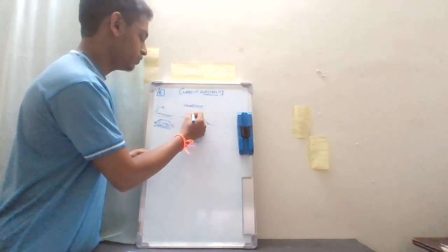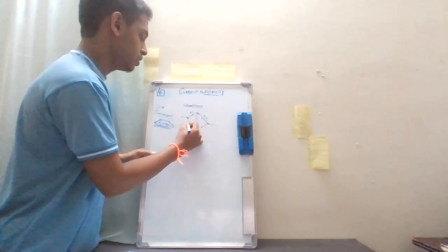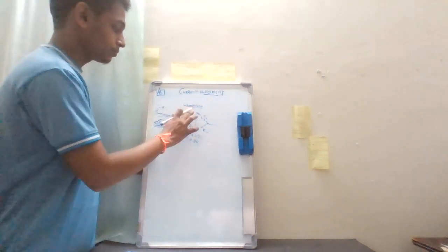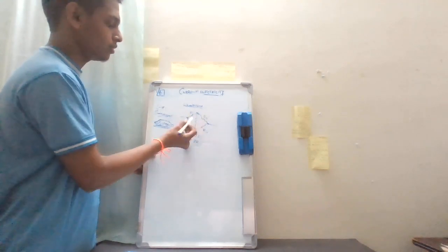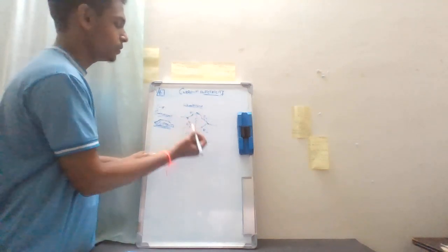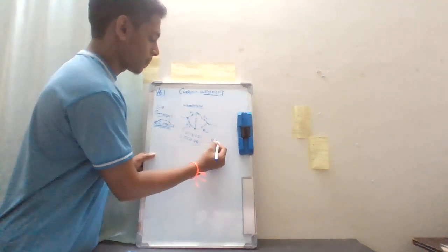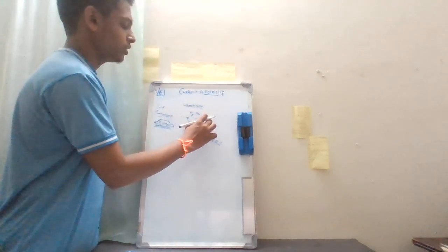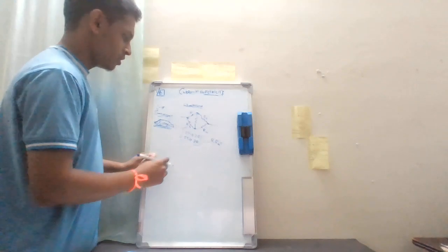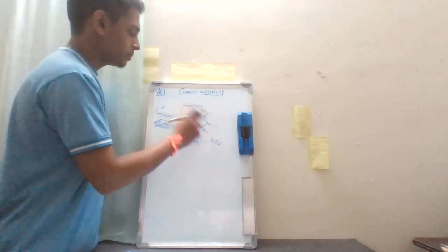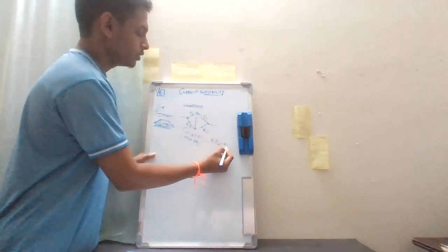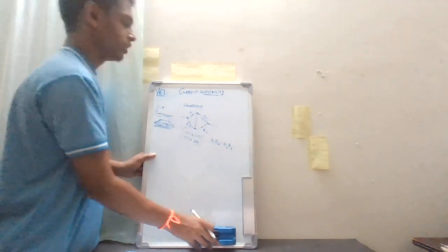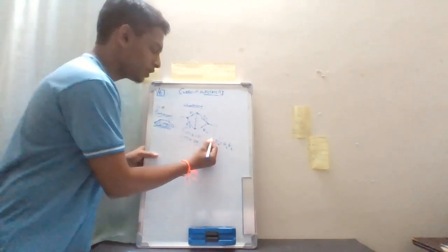Here we name the resistors R1, R2, R3, R4. R1 into R4 should be equal to R2 into R3. The product of two resistors should be equal to the product of the other two resistors, which are completely disconnected and have no common points.